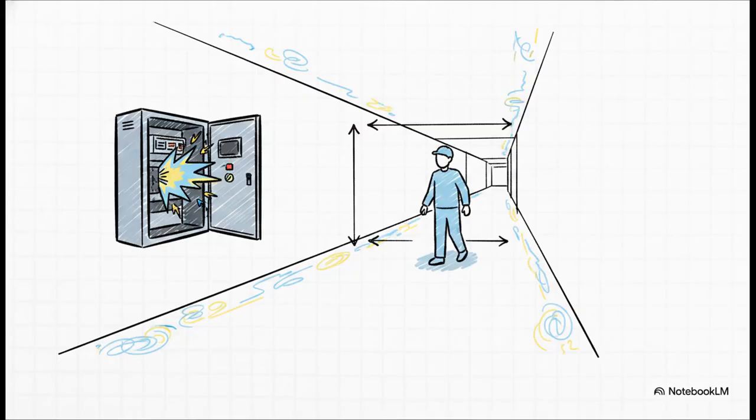So, the crucial point is really hammering home these exact measurements for the exam. Your egress path must never be impeded. Even with panel doors open, the escape path cannot be reduced to less than 24 inches wide and 6.5 feet high. Furthermore, the floor in that working space can't be a tripping hazard. It must be kept clear, level, and as flat as practically possible.